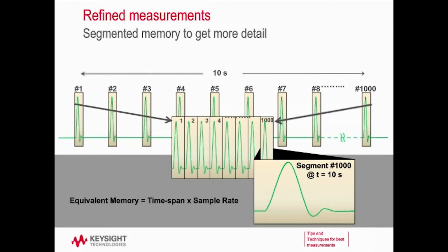We'll talk about a tool that we have on Keysight oscilloscopes called segmented memory. Essentially, this allows you to selectively capture parts of your data bus. Anytime you trigger, it's going to capture just that amount of signal on screen, and we're not going to care about the dead time between pulses in this example. Instead of wasting my memory depth on that dead time between pulses, I can just capture the parts of the signal that I care about and then make measurements.